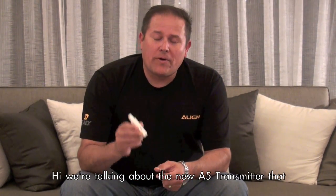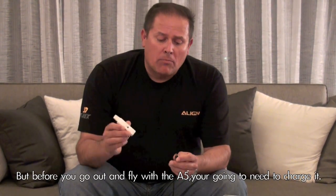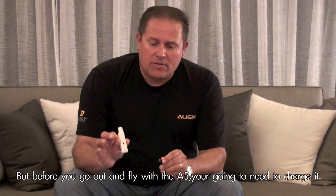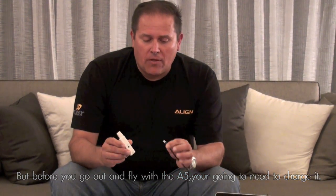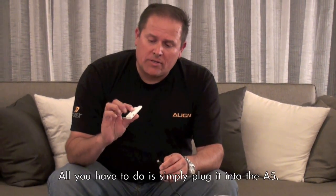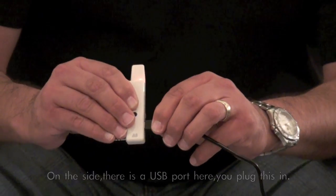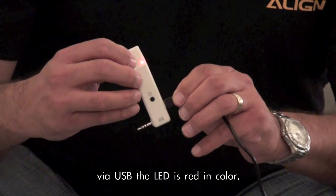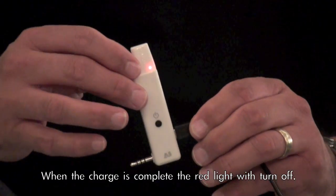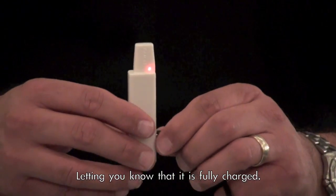Hi, we're talking about the new A5 transmitter that enables you to utilize your iPad or iPhone to fly the new TREX-100. But before you go out and fly with this unit, you're going to need to charge it up. There is a USB cable included that will plug into any standard USB port. All you need to do is plug it into your A5 here on the side. There's a USB port here. You just plug this in, and then you'll have the LED that's red in color. Once it's completed its charge, it will turn off and let you know that it's fully charged. So you just leave that plugged into your computer and it'll charge that up for you.